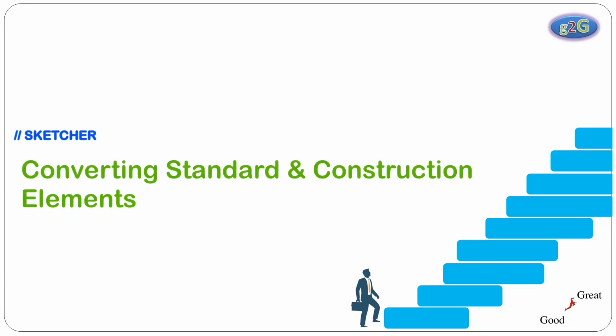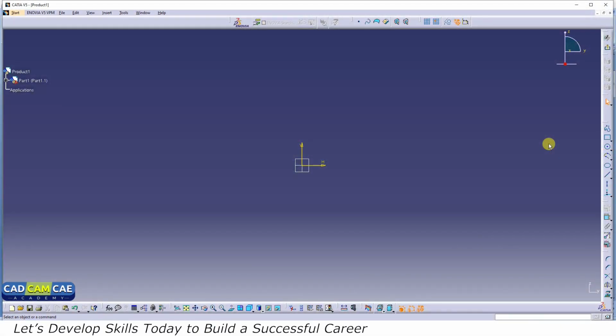So now let's see how to convert standard element to construction element and vice versa. For that, let's create a standard element. Let's try to create a rectangle. Now if you want to convert any of the edge into construction element, you can do it by using a command construction standard element. Now let us try to convert this standard element into construction element. So click on this element and click on this command.